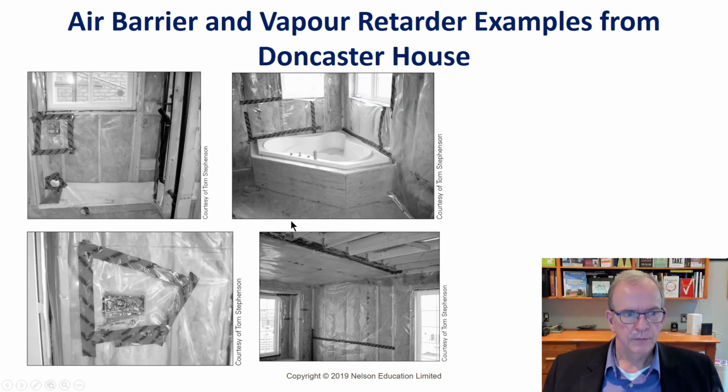So here you go. This isn't all that great a job, but you can see the tuck tape, you can see the poly, you can see how it's wrapped around the boxes. As I'll show you in a minute, you can do better than this because there are special boxes that self-seal. These things leak like a sieve. Those electrical boxes are always a challenge.